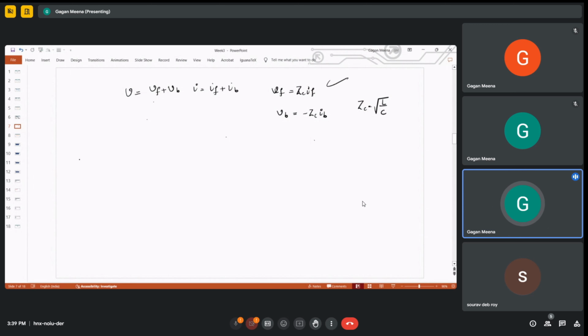Then next we saw the surge power input and the energy storage. The surge power input will be P equals V into I in watts. Here we have the electrostatic component. Since the receiving end is open circuit and the line is assumed to be lossless, the energy input per second is equal to the energy stored per second.